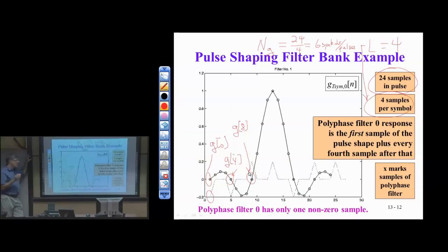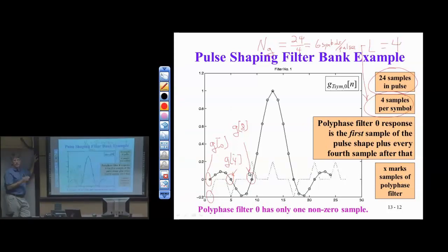Now this comes back to the earlier question: if we upsample and then apply an FIR interpolation filter, how do we know that the original samples are not changed? The original values before upsampling were not changed. Is there a special pulse shape, or a special condition on the impulse response of the FIR filter? The answer is yes. Essentially, the values at the start of the symbol periods in the future and the past have to be 0. That is to say, we don't include contributions from those particular values. If we do that, we don't in any way affect the original sample values prior to upsampling. They are carried through the whole interpolation process. If I don't get the zero crossings here, then I do change those values. Not the end of the world, but it depends on the application.